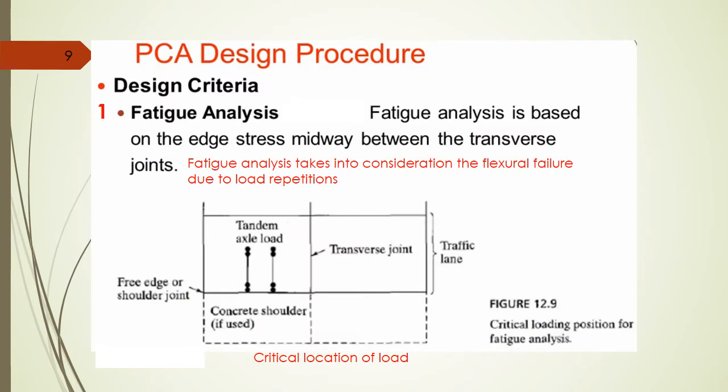Our first design criteria, fatigue analysis. Fatigue analysis is based on the edge stress midway between the transverse joints. Fatigue analysis takes into consideration the flexural failure due to load repetitions.